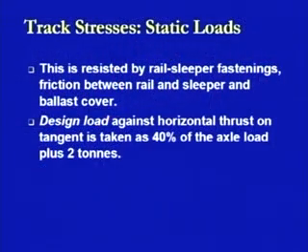Now, when we are talking about all these lateral forces, as we have just seen, there can be a twisting or bending condition at the foot of the rail section. It is going to be resisted by certain fastenings by which that rail section is fastened to the sleeper. Therefore, the total amount of this load is going to be transferred to those fastenings.